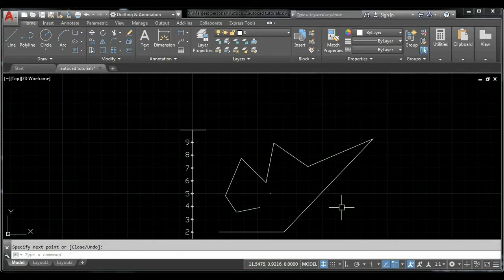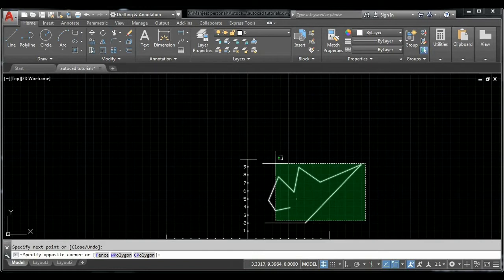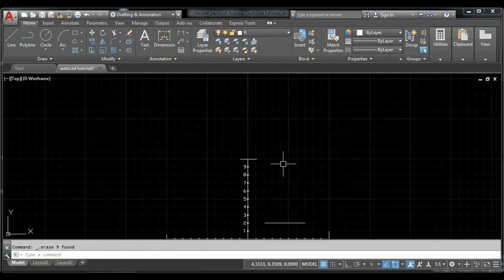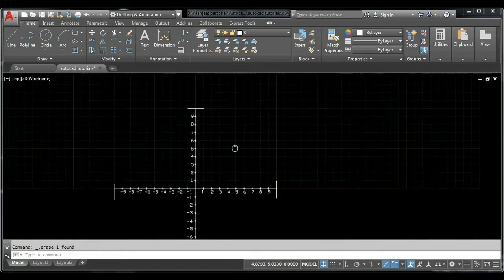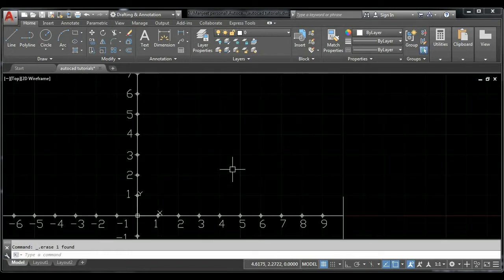If I want to make a line at an angle, then what I can do is use angle overrides. Now how to use angle overrides? For example, I took the line command, L, enter. So I specified my first point. Now you can see it is rotating freely around the space.